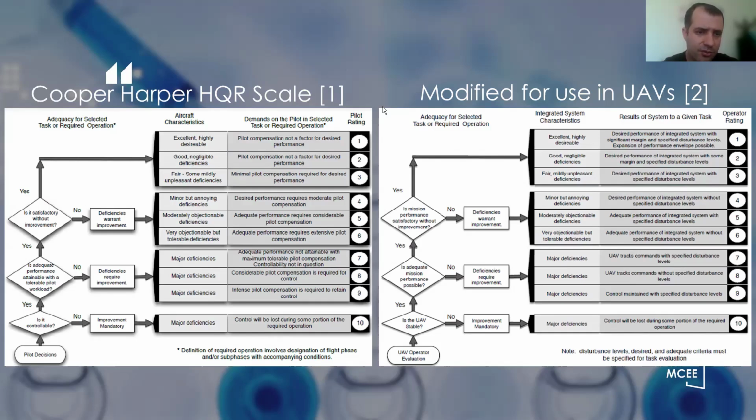It attempts to evaluate an aircraft's handling qualities based solely on qualitative data. By sequentially going through the Cooper-Harper scale, engineers hope to receive specific diagnostic feedback on how the aircraft performed a particular task.